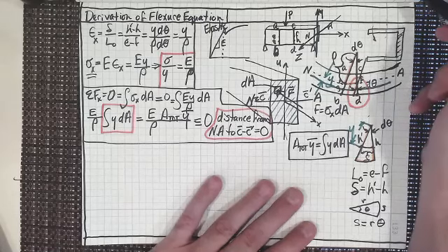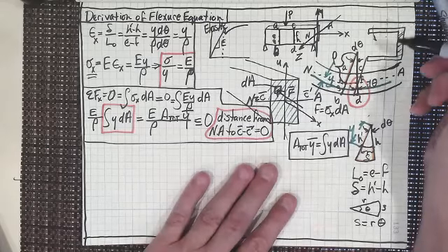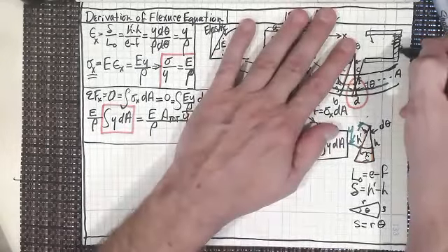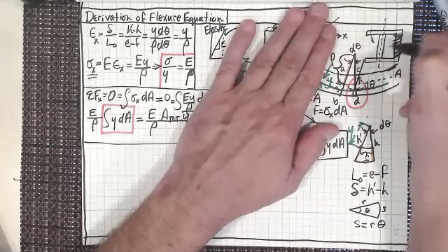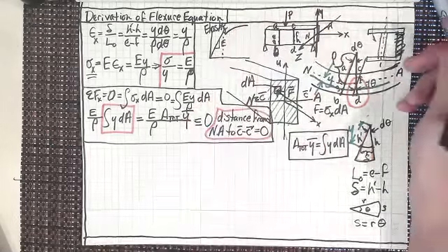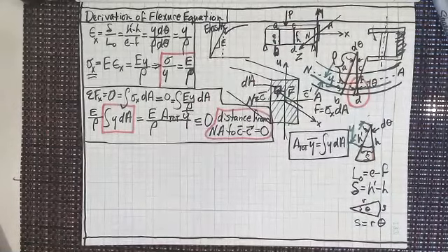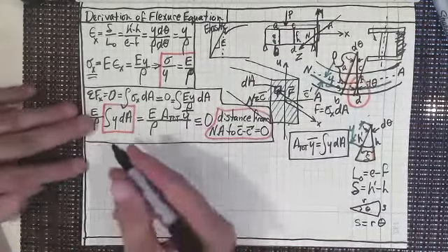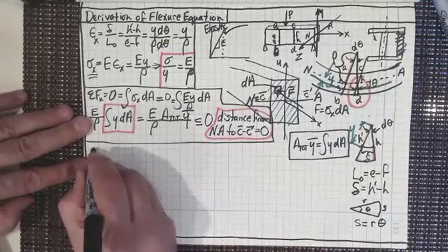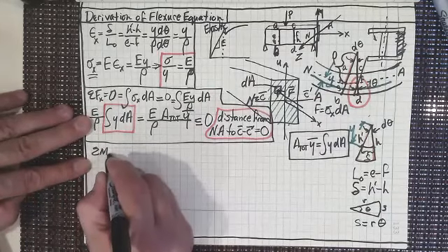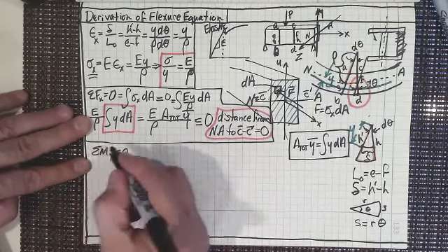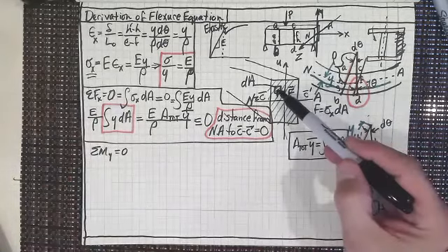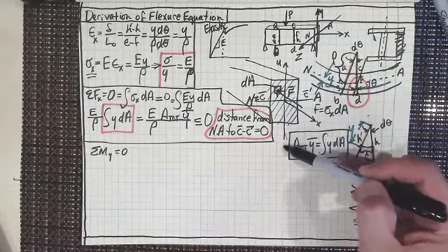That's why what I'm going to show you right now is why we don't make things like this. We make things predominantly symmetrical about the y-axis, right? An I-beam is symmetrical about the y-axis usually, and that's so that we don't get any moments about the y-axis. So what I'm assuming is that the moments about the y-axis are going to equal 0. And how do I make sure of that? Well, there you go. So this is the y-axis right here.